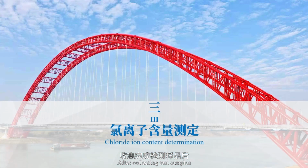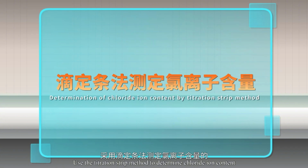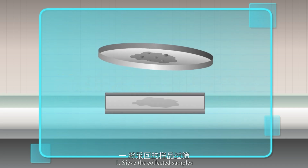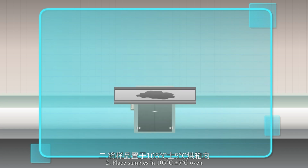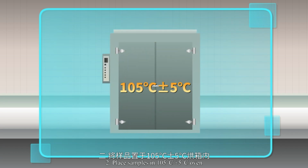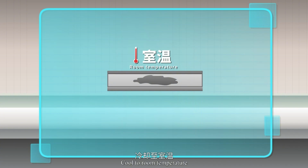After collecting test samples, we adopt the titration strip method for chloride ion content determination. Next, we will examine an animated demonstration of the test process. Use the titration strip method to determine chloride ion content. The analysis steps are as follows. First, sieve the collected samples to remove larger particles. Second, place samples in a 105 degrees Celsius plus or minus 5 degrees Celsius oven. After drying for 2 hours, cool to room temperature.